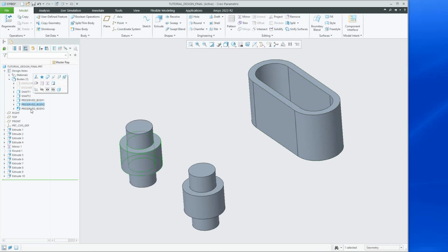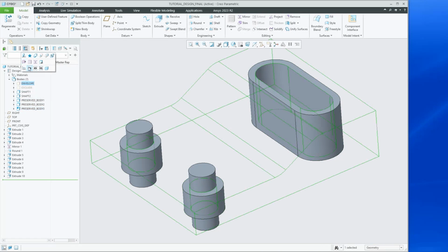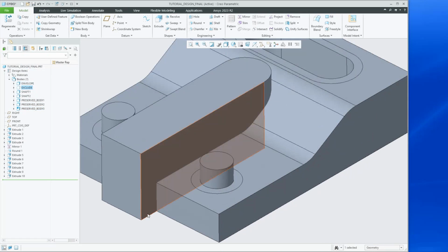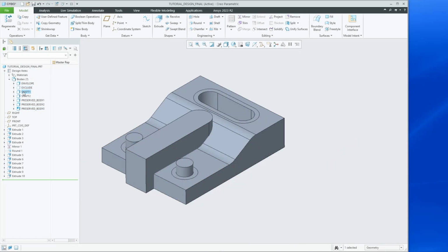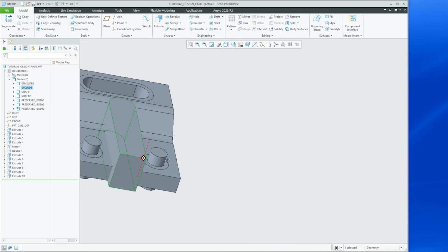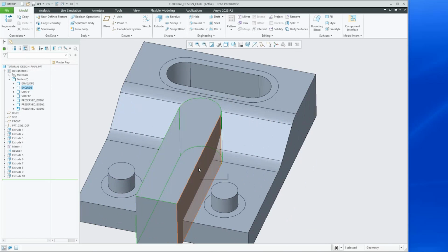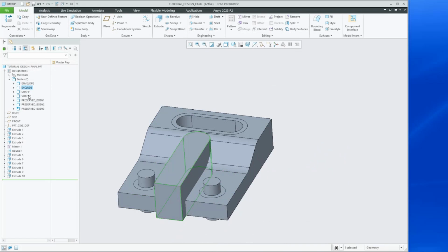And then I've got these other preserved bodies where the design intersects with those shafts. So let's turn this on again. Now, also, it's hidden at the moment. I'm going to turn on... I'm going to say that this region here, in the middle, is a preserved region. So I want this to actually be moved outside. This one is like a keep out area. So I want to make sure that the optimized geometry is outside this region.